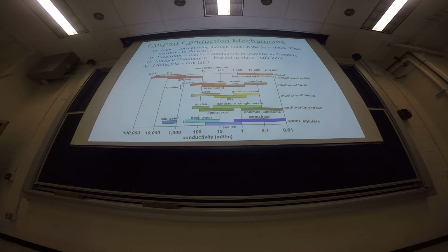And in most cases, that water, that fluid, will have dissolved ionic species, whether it's normal sodium chloride or potassium chloride. But basically, water is a very good leaching agent, and it leaches out ions into solution. And it turns out those ions carry a charge, and therefore can conduct a current. So the most dominant electrical conduction mechanism you will see is what's known as ionic.